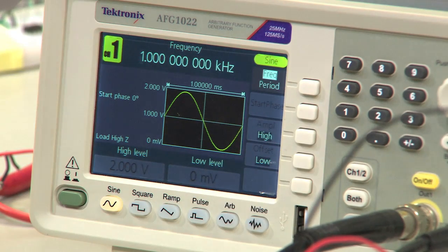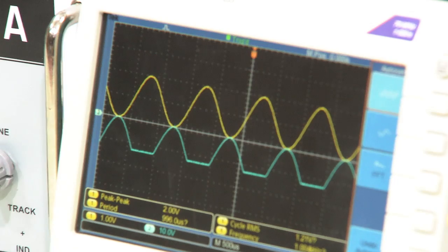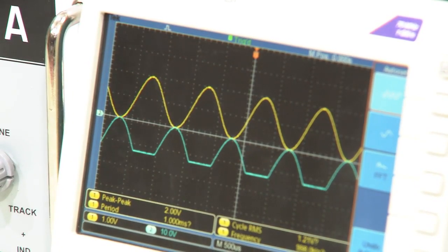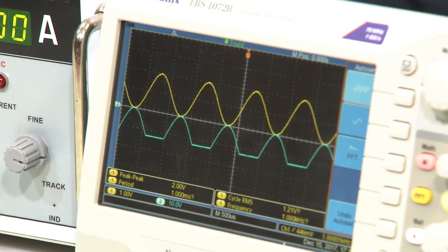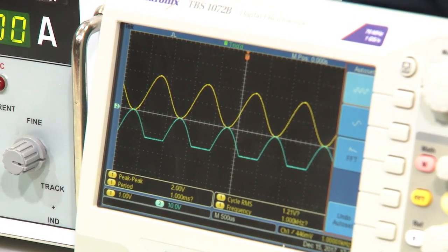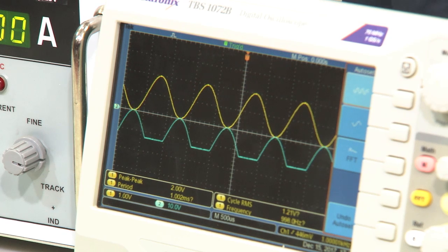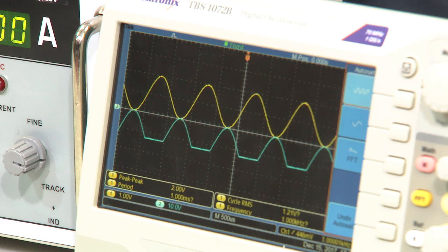When we apply 2 volts instead of 1 volt, what is the output? Let us see, alright. If you see in the oscilloscope, it is clipped. Now, the first question that should come to your mind is, how many times did it amplify? We found the gain was RF by Rin, right. So, 10 by 1 is 10, 10 is your gain. How much voltage are you applying? 2 volts, 2 into 10 will be 20 volts.